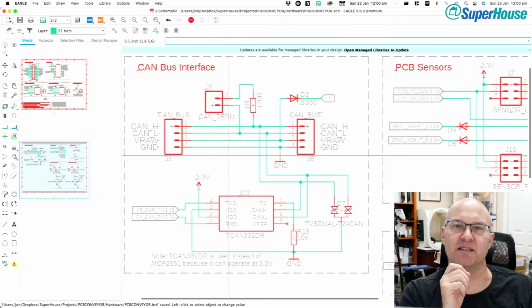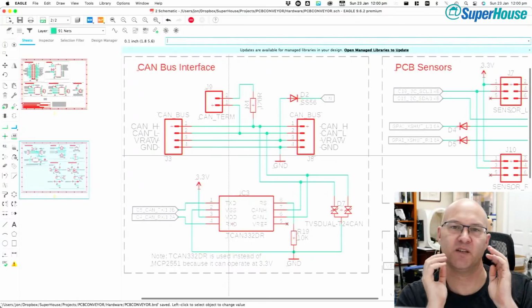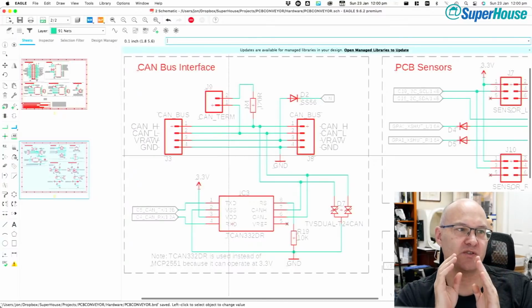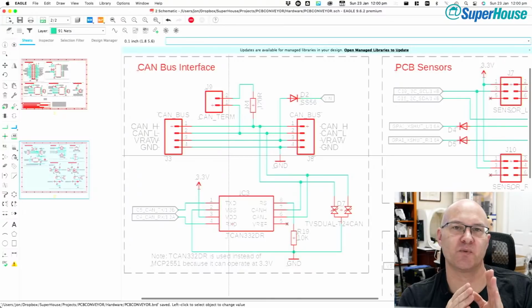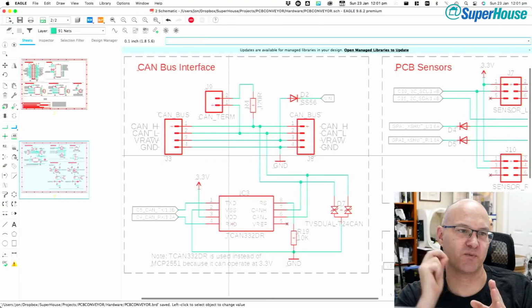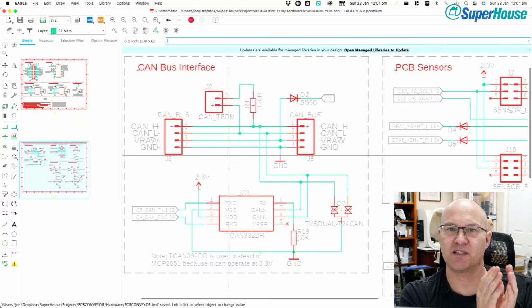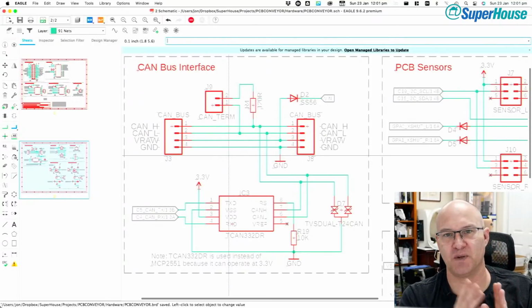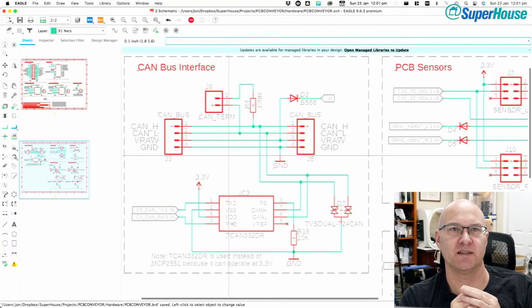Now the same applies with non-electromechanical systems, with things like if you have two MOSFETs and you put them in parallel because you want to switch a high current load, there can be some issues where you have different characteristics in them. One switches on before the other, and even though things like MOSFETs are very, very fast compared to something like a relay, which is mechanical, it's got to physically move, you can still have similar things go wrong. And you can end up with a bit of a cascade failure effect.